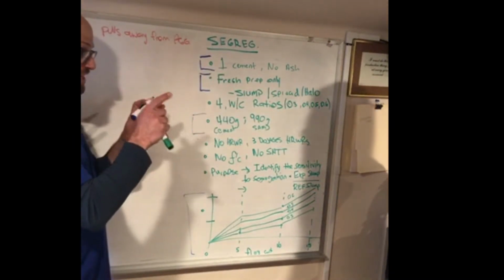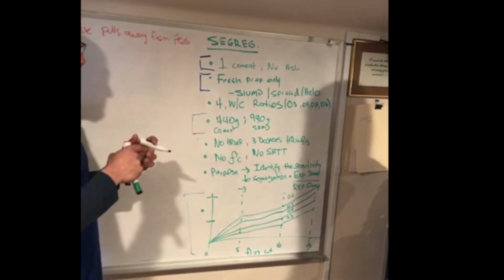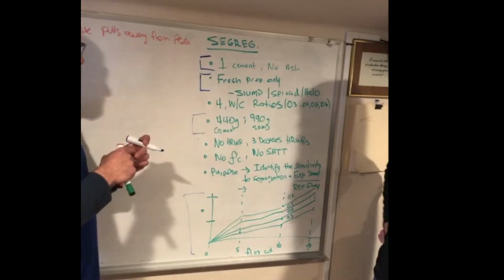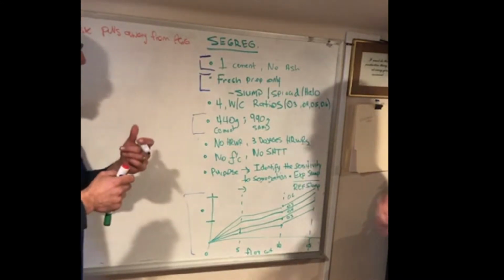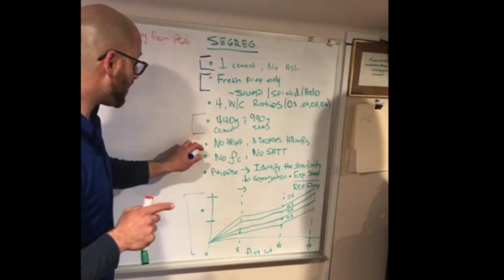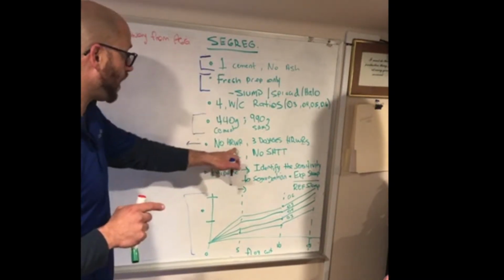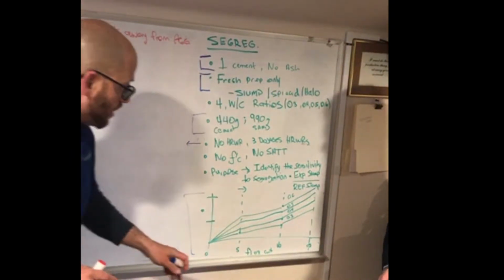With your current training, what do you think is going to happen as we increase the water cementitious ratio? The slump is going to grow larger, the spread. Right. Awesome. Good job. So, based on that, we're going to have 1 reference with no high range, and then 3 increasing dosages of our high range water reducer.